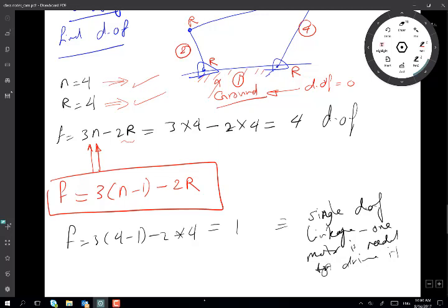But also we can describe the position of any point on the linkage if we knew one parameter, and normally this one parameter would be the angle made with the x-axis by the link which is going to do 360, which we refer to as the crank, because normally you attach the crank to a motor.